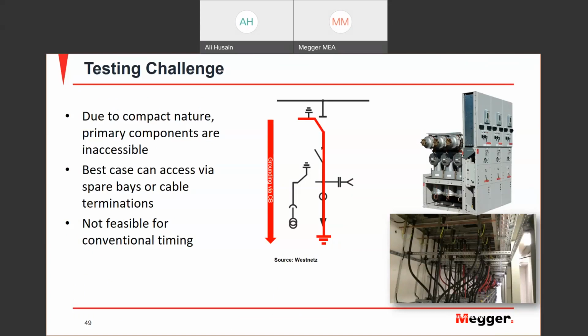It's just difficult to connect to them. There are no terminals that you can connect across the breaker to do the timing test. You have to open the whole assembly, and that's a very tedious and difficult job.